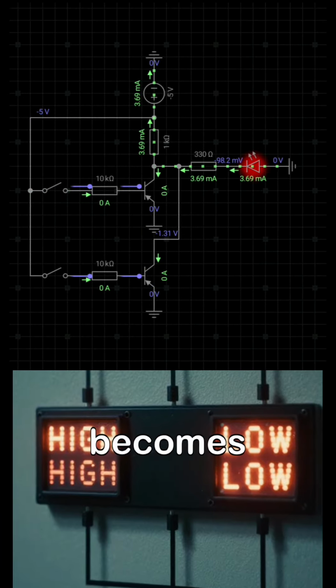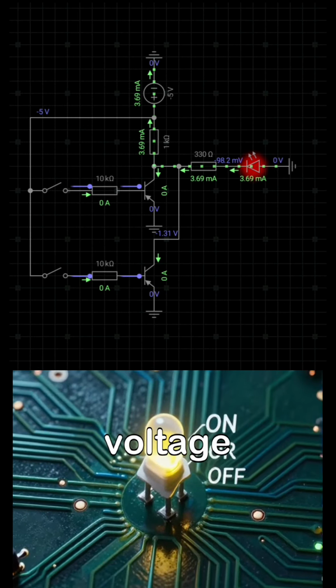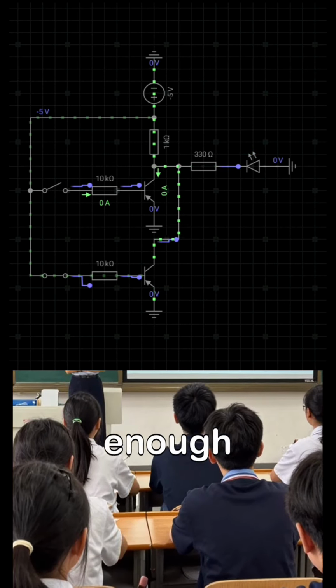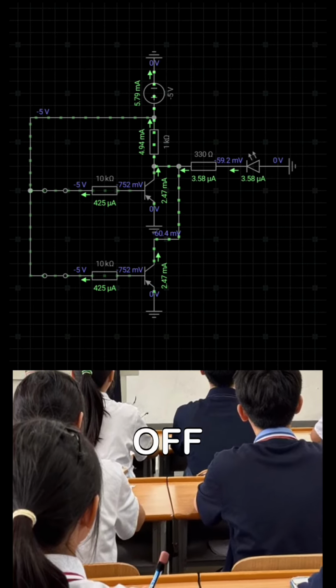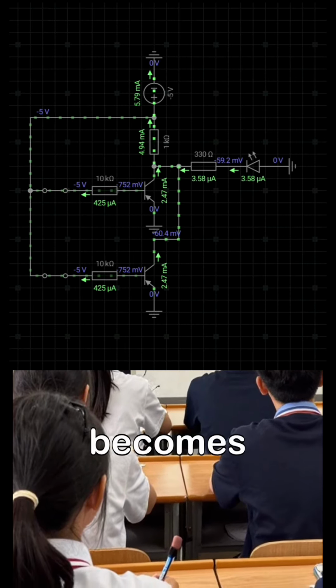When any one input becomes high, that input raises the base voltage. Now the base is no longer low enough to keep the transistor on. The PNP transistor turns off, current stops flowing and the output becomes low.